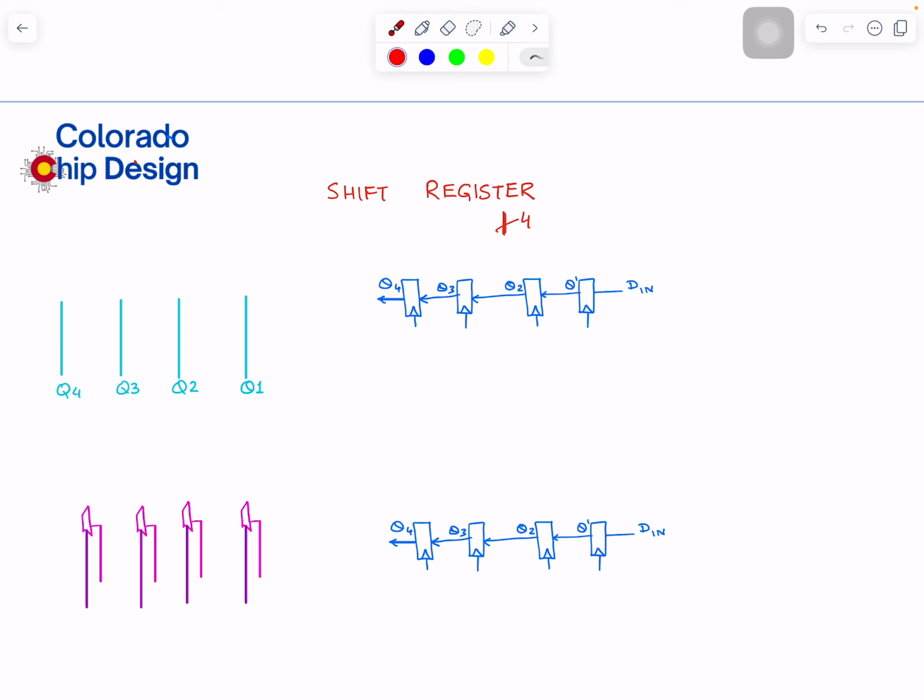So this bit when it comes, let's say is 0 initially, and this thing is 1. After we have a rise edge of the clock, since all the flip-flops have no bubble here, they will move data from here to here on the rise edge of the clock.